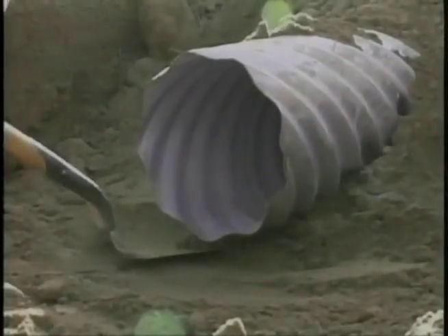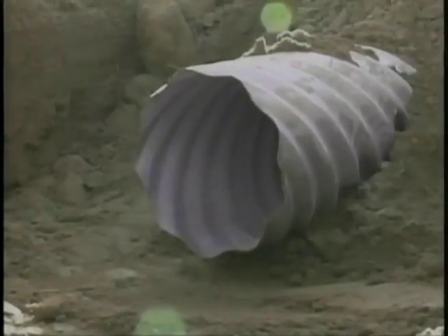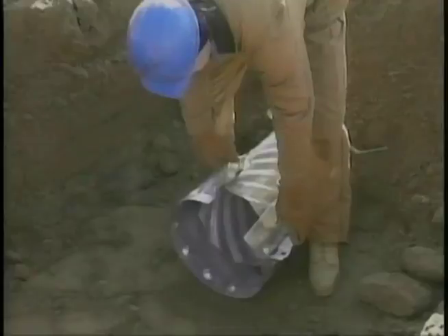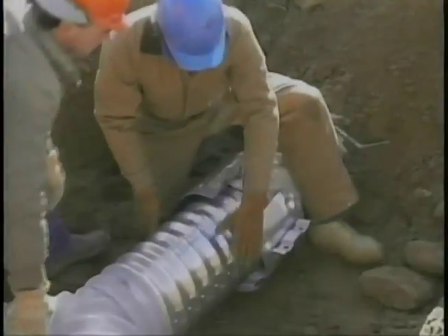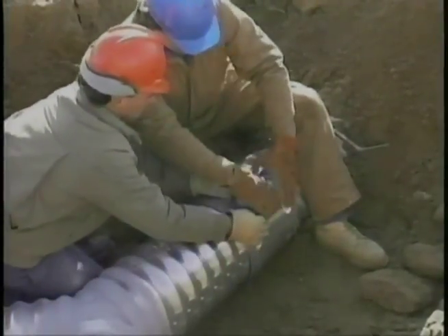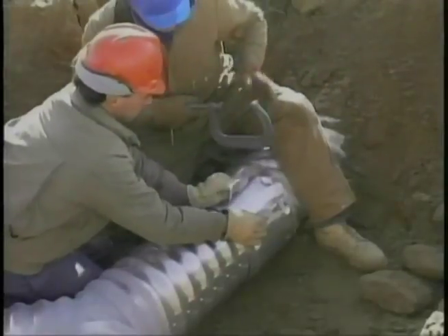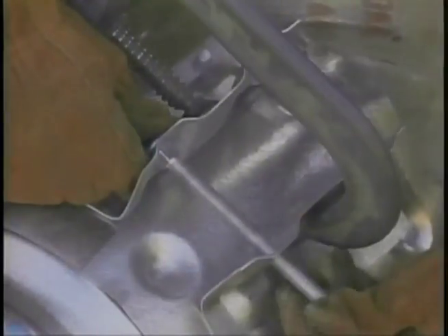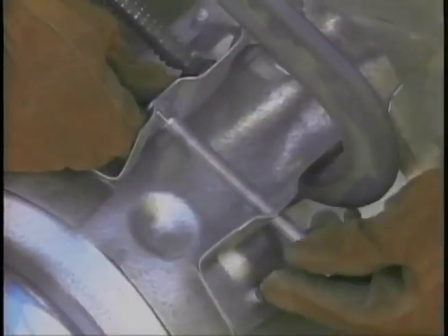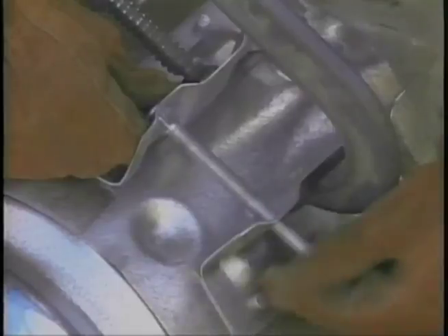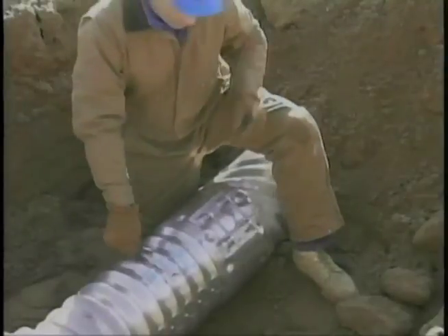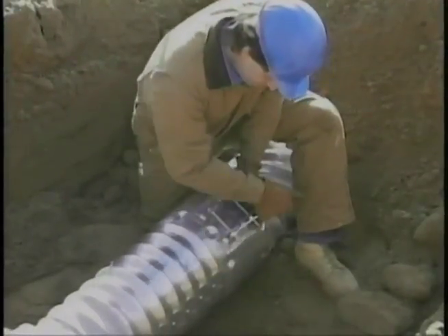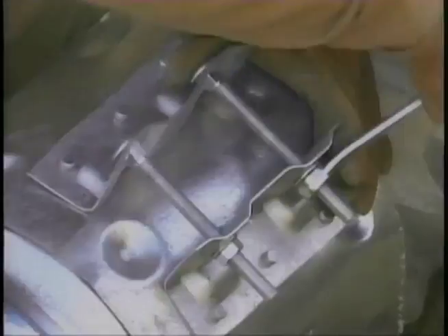Dig around the existing pipe, allowing room for installing the coupler. Clean the pipe and center the coupler over the end. Lower the next length of pipe into place, spread the coupler apart, and butt the ends of the pipes together. Place a C-clamp against the bolt brackets and draw the brackets together. Insert the bolts with the thread ends pointing down. Hand tighten the nuts up to the bracket. Remove the C-clamp. Tighten the bolts evenly to hold the coupler and the pipe ends together as a unit. Do not over-tighten the bolts because the brackets will break off from the coupler.